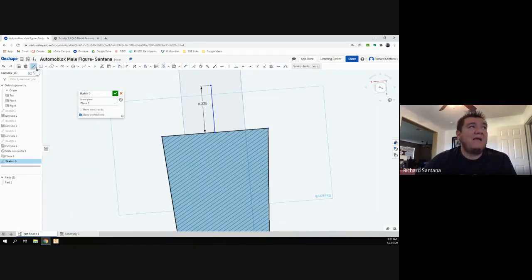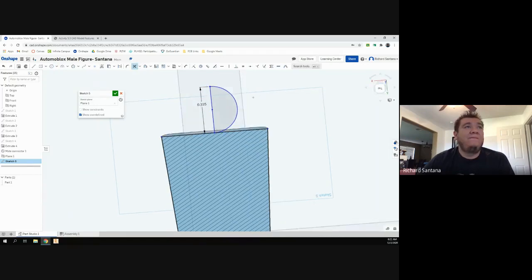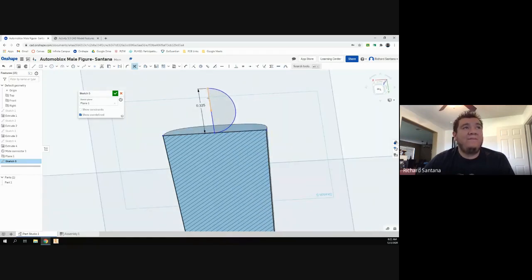If you guys haven't already used the arc tool, maybe it's worth your time to try to figure out, see if you could do a pretty good job. In this case, maybe the arc tool is not the best option. What I normally do is I grab the circle tool. I go to here. I click it all the way up there, and I trim off one side. You'll see that we have this D shape here. And the reason I trim off the side is because you can't revolve a full circle. You need a line to revolve it around.